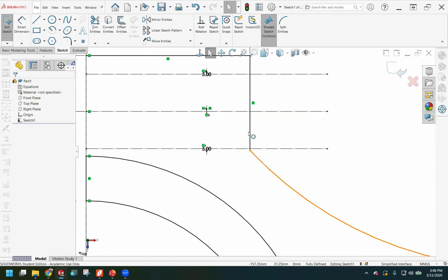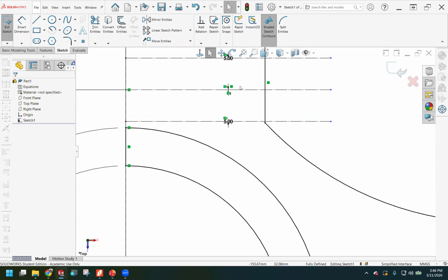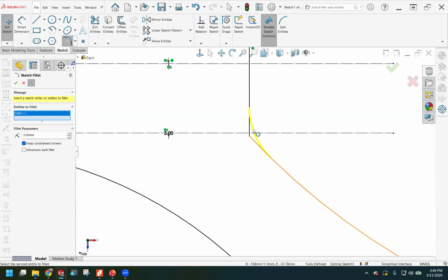And this fillet coming in, as drawn in the book, there is a hard edge here for a nut or a bolt to connect to. And I think that's a good thing. But the next piece that we're going to add to our puzzle is this part specifies a radius 5 fillet at that connection. So right in here. And as you can see, this is going to cause a curve to begin where it's going to slightly overlap the edge of that hole.